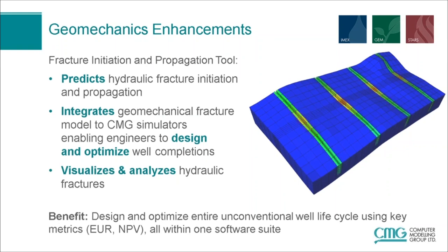And if we cross the threshold for hydraulic fracture formation within the geomechanics grid, we can see the nodes of the grid block split open, and we can see the hydraulic fracture being formed. And then this can be translated to a permeability increase in the flow simulator. And so you can see from the image on the slide, we can actually visualize this process as well. So this is a video taken from our new results software in 3D, and we can actually view the hydraulic fracture formation in time, which helps us analyze the hydraulic fracture formation.